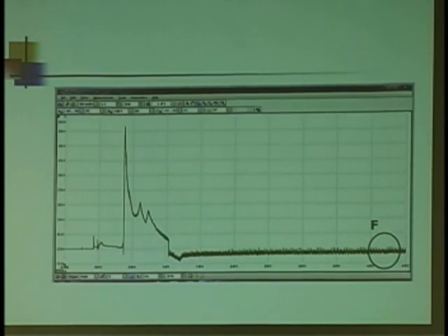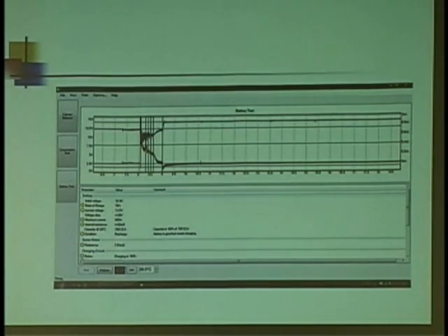If you see anything more than 3 amps net, then you've got a sulfated battery. Those are the batteries that test good today and test worse than crap the next day. These are the batteries that cause alternators to fail repeatedly. If you see a 10, 12 amp net, those poor alternators are going to overheat. And now again, you have a graphical representation. In fact, with the PicoScope, you can actually print out a report for the customer, but you don't need all that. Just save the screen, send it to your printer, and print it out.